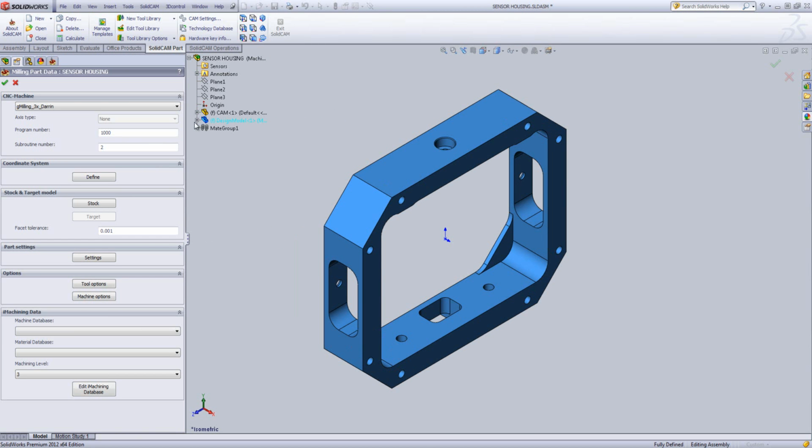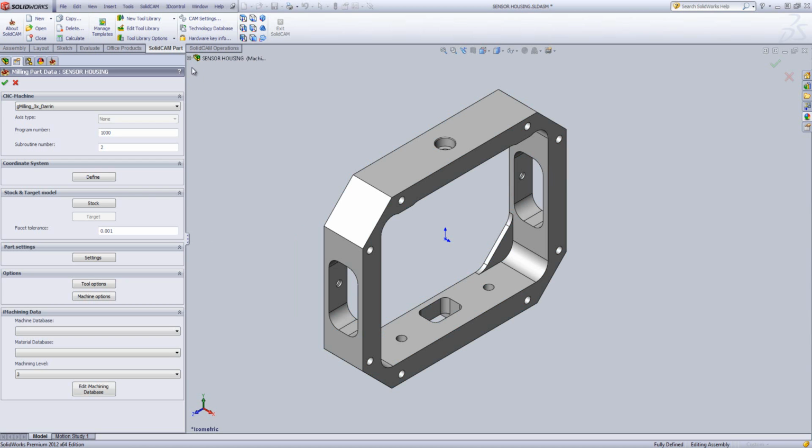Since we are now working in assembly mode, you have the option of working on an entire assembly or multiple parts in that assembly, and you can also import any fixtures like a table, vise, parallels, etc. that you may want to use for gouge checking or selecting the part levels from. For all new users, I suggest working in manual mode. I always work in manual mode because I prefer to see the revisions made to the model and which toolpaths were affected by those changes.